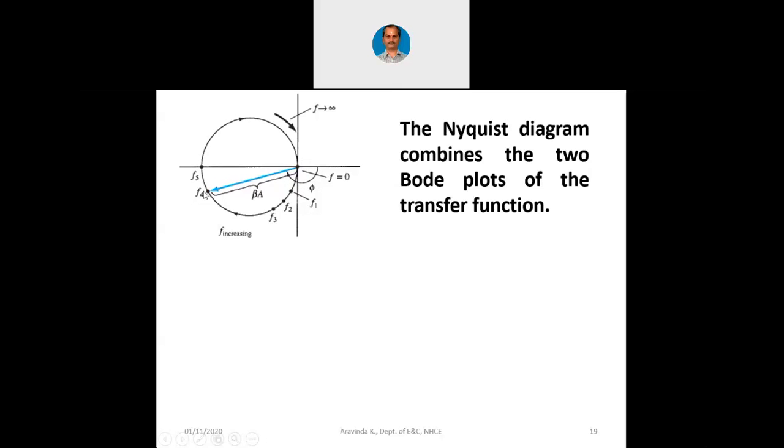Now what is this A beta? A beta is the gain factor, right? We already have this particular terminology, A by 1 plus A beta. A into beta. A is the gain of the amplifier. Beta is the fractional part of the output taken out at the feedback circuit. Now A into beta is a factor here, and Nyquist had indicated in that formula that when A beta equals -1, then we have infinity feedback gain.